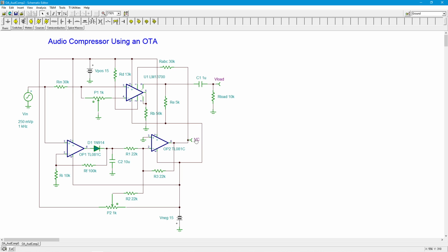So the bigger this voltage is, the more gain this amplifier produces. Now, I've set this up for a signal that's maybe no more than about a volt, which is what you would expect on a guitar or a bass typically. Depending on what you're using, you might want to do some mods over here on the front end.